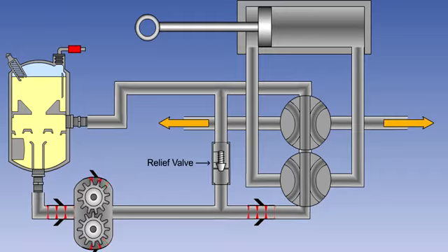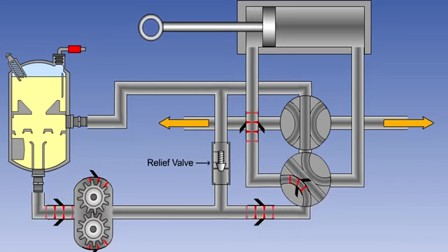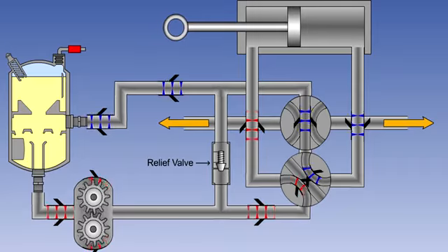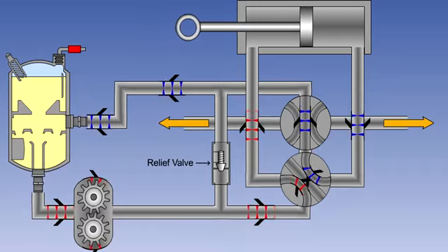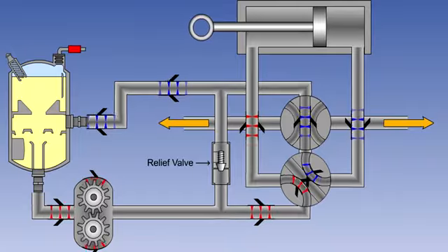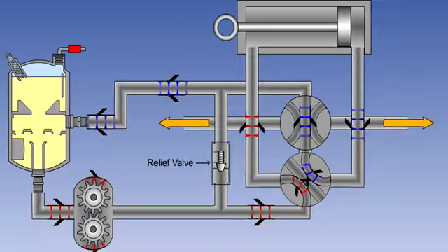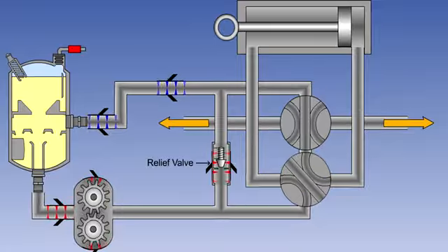On selection of a user system, the fluid is directed to the actuator, which will move. The fluid from the other side of the actuator will return to the reservoir via the central port of the second selector. When the actuator reaches the end of its travel, the selector is returned to neutral in order to offload the pump and allow other services to be selected.